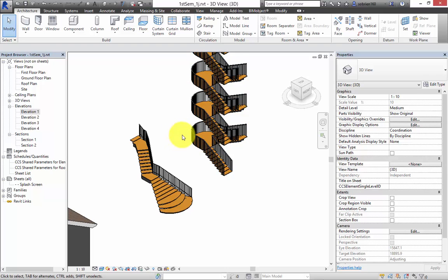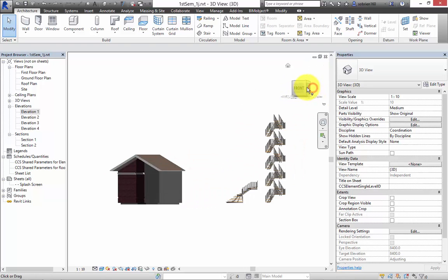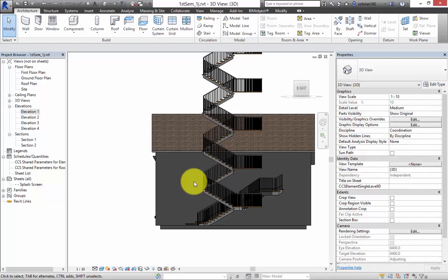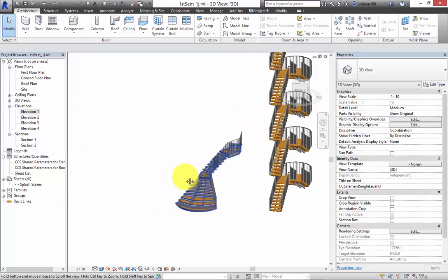Can you build different stairs in each story? For example, the first floor is something like this one, and the second one is something different. Yeah, you can. It just means that you can't use that multi-story option, because it'll just copy it up. You can do whatever you want. It's just a shorthand for an office building or something like that, where you want to do it quickly.